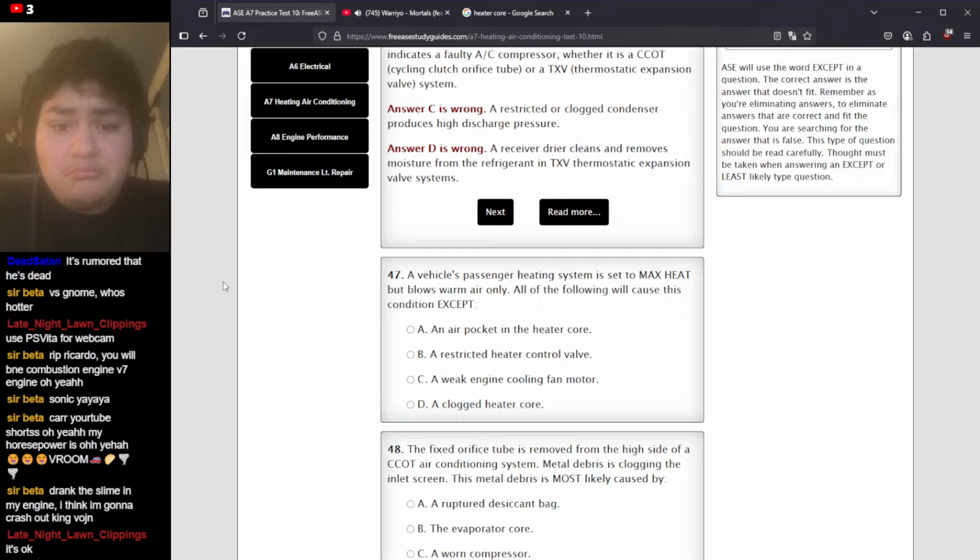It basically uses the engine's heat from the coolant, and it passes through the heater core, and from the heater core it goes back into the radiator or something. And so your heater core uses coolant, right? And not Freon. It uses coolant, and not water or anything. It uses whatever's inside your cooling system.